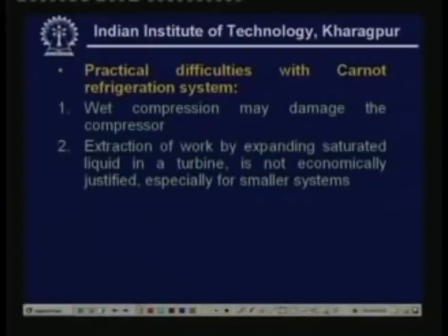That's how you get an isentropic expansion process. But what is the work output during this process? If you assume that the process is a steady flow process, then the specific work output of a turbine, if you are neglecting kinetic and potential energy changes, is given by the integral of VdP.